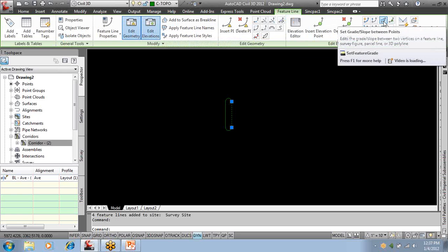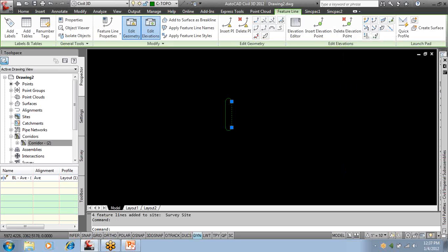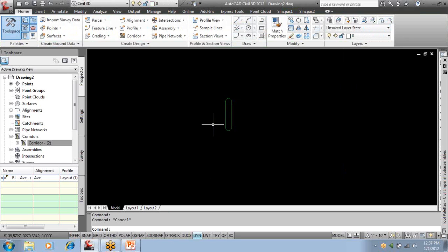When you do site design, use this icon. There's a little blue triangle after you pick edit elevation. It allows you to pick an elevation for your site design around the whole outside or every curb on it. You assign a starting elevation. You can say down 2%, up 2%, down 2%, up 2%. You don't have to type every elevation individually. So those are really the easiest way to honestly do the curb island. You move it up to the existing site and then put in the elevation.